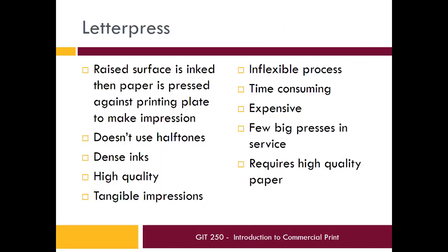So the key thing here is, one, that letterpress does not use halftones. The ink is spread out evenly over the entire raised surface of whatever you're using here. And so the result is that you cannot print full color stuff here very well at all. If you want colors, you just use that color of ink. You mix the inks themselves. It's very nice and high quality looking.